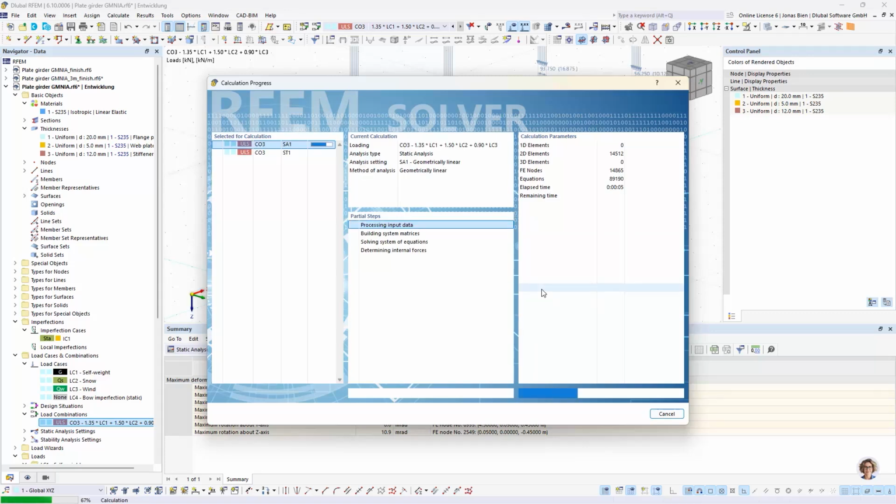So it will now, after defining the stress state in my structure, calculate the linear bifurcation factors, assuming everything is perfectly linear. So my whole problem is linear, and besides the linear bifurcation factors, I will also receive my respective mode shapes.